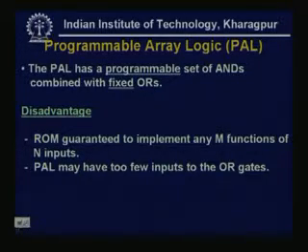For the M functions, any set of the 2 to the power n minterms is available. PROM guarantees that, but a PAL may have too few inputs to the OR gates, because it has a programmable set of ANDs combined with fixed ORs.